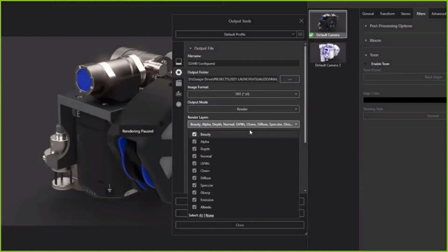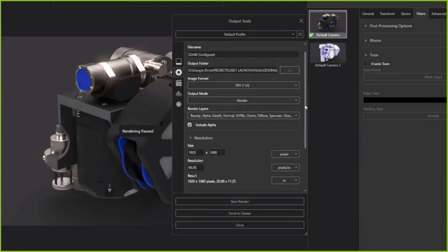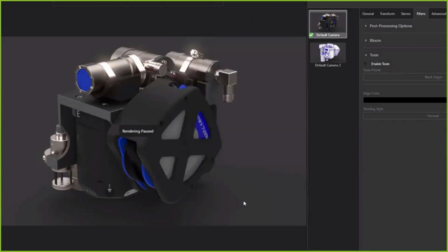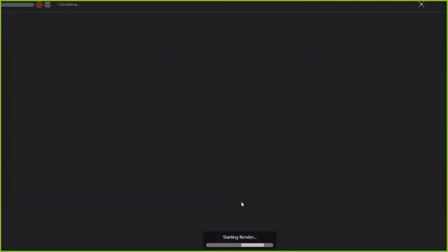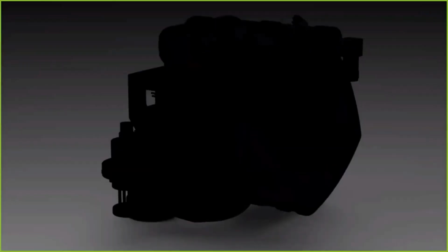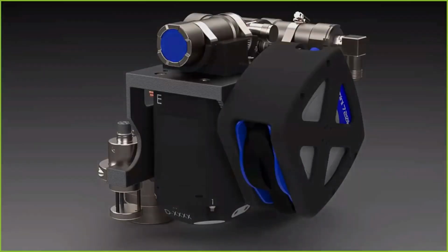When it comes to creating renderings, nothing beats the speed of Visualize's hybrid rendering engine coupled with our AI denoiser. Previous releases of Visualize allowed you to generate rendering passes for specific rendering layers, such as beauty, alpha, ambient occlusions, and so on, which would each require their own rendering process. So what's new now, this workflow has been streamlined by generating each of these requested layers in a single rendering output.